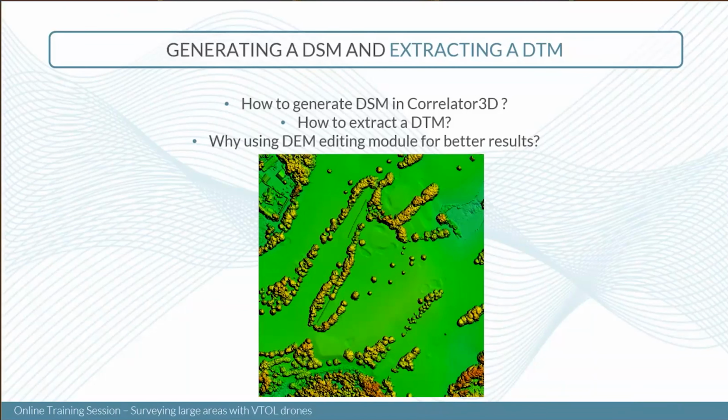If you go lower than 3 times the GSD, like a pixel value, a one-to-one matching, you will maybe add a bit more noise to your project. So we don't really suggest going below 3 times the GSD of your image for the DSM resolution.